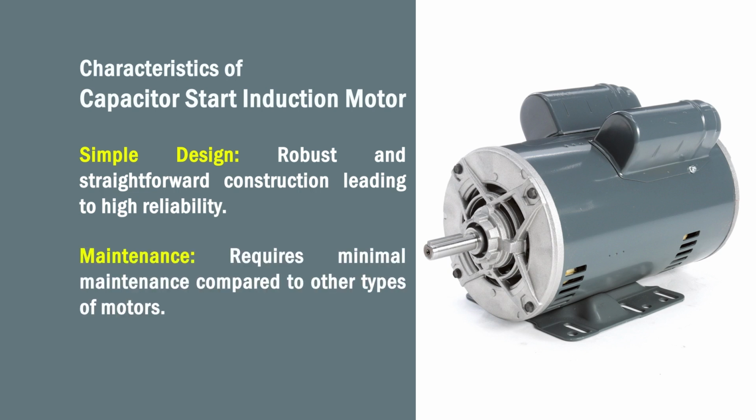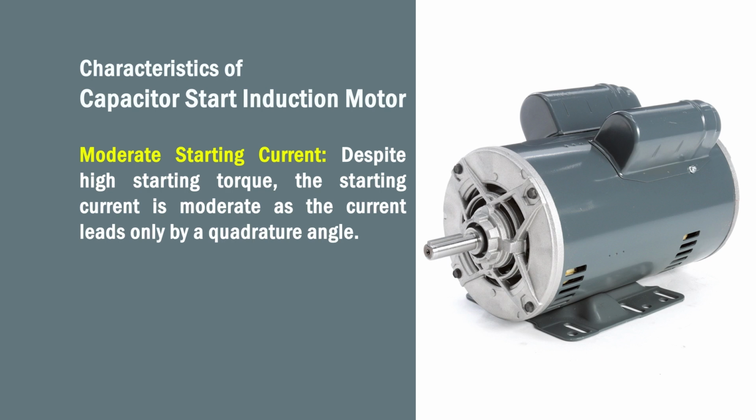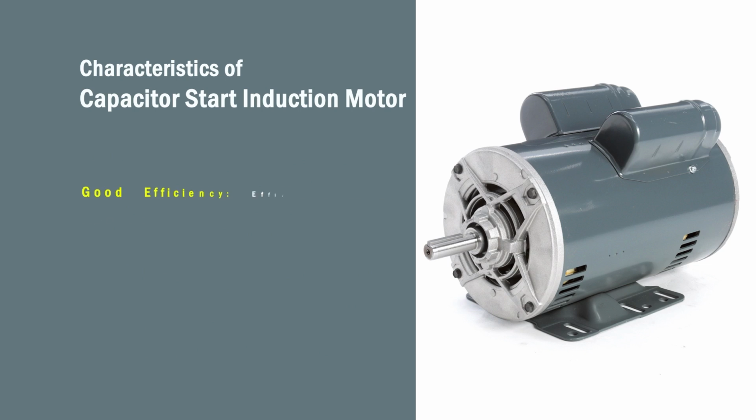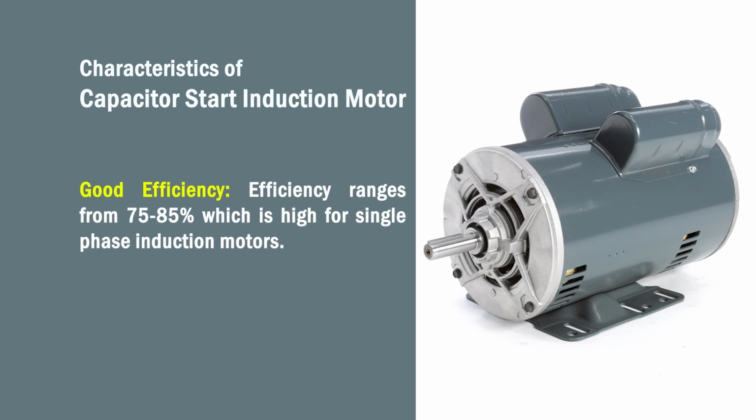It requires minimal maintenance compared to other type of motors. It is having moderate starting current, that is despite high starting torque, the starting current is moderate as the current leads only by a quadrature angle. It is having small power factor, that is during starting the power factor is between 0.2 to 0.4 due to the leading current component. It increases to nearly 0.8 at full load. It is having good efficiency, that is efficiency ranges from 75 to 85%, which is high for single phase induction motors.